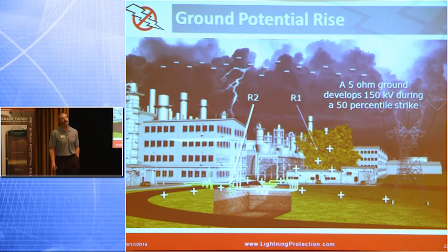In general, we're going to talk about grounding design, grounding principles later on. But in general, as a standard design protocol for lightning protection, you want to have common grounding. So if you grab the NFPA 780, National Fire Protection Association 780 standard, it's going to talk about the need for common grounding. They don't talk about what type of ground resistance you want for that ground grid. In other words, NFPA 780 doesn't say you need a 5 ohm ground. We kind of say you should have a 5 ohm ground. But they do say you need common grounding. So you don't want to have two different grounds.